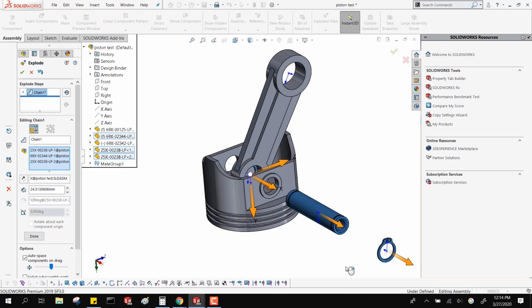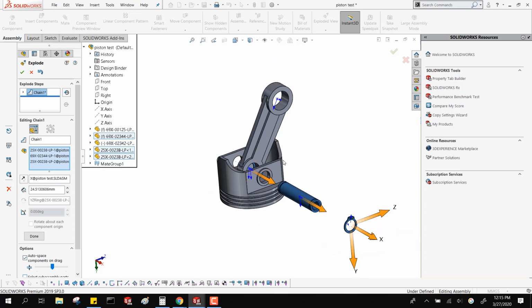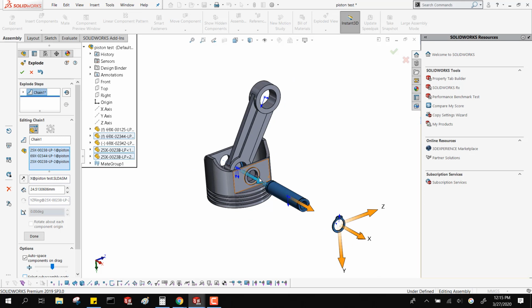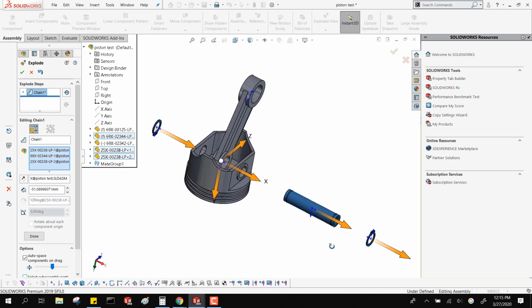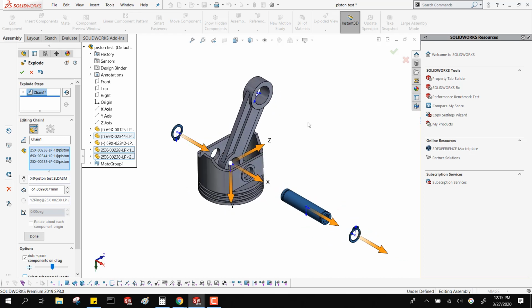It telescopes each part. How far it telescopes has to do with this setting that you've got here, a little or a lot. It's always going to get it wrong. That's why it leaves these little arrowheads for you, so you can fine tune it to get more of the view that you were after, like right there.